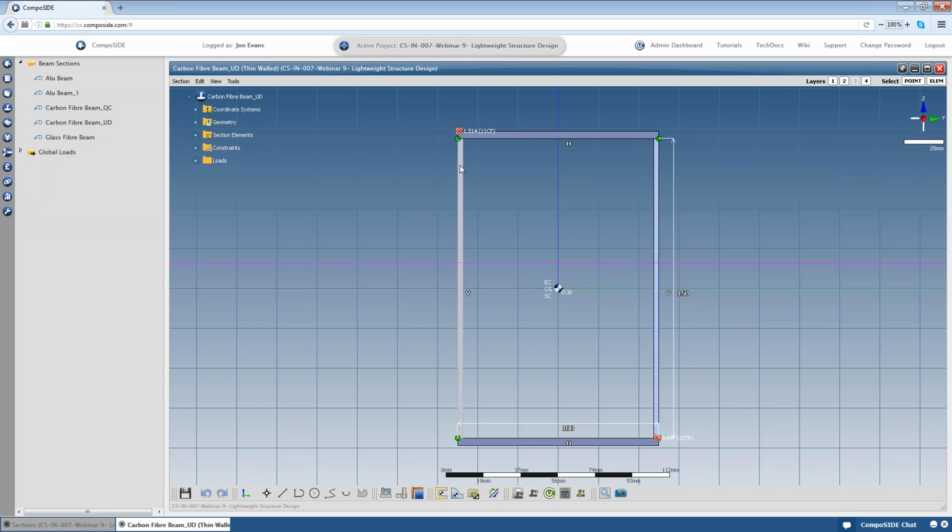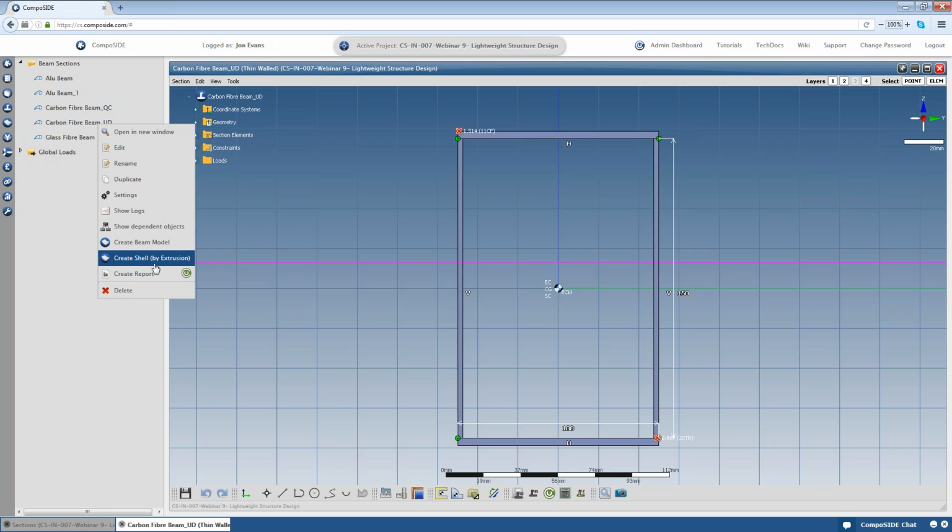Okay, so these walls are looking fairly thin. If I want to do a quick check to see if they buckle, because they're okay in strength reserve factor, but I'm not sure about stability, what can we do? We can use FE space to do a quick panel check by extruding the beam directly from section space. This gives us our geometry and our laminates. I've done this earlier. Let me save this and then we'll jump into FE space.